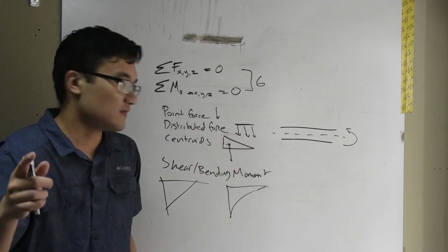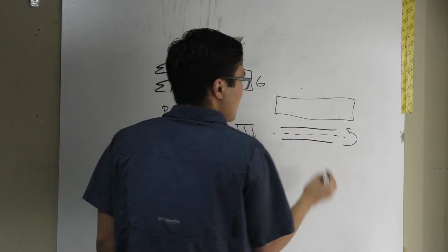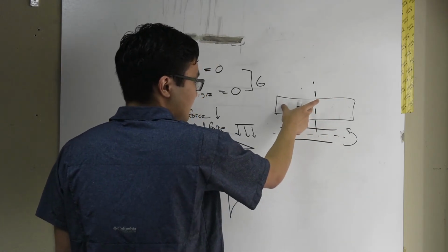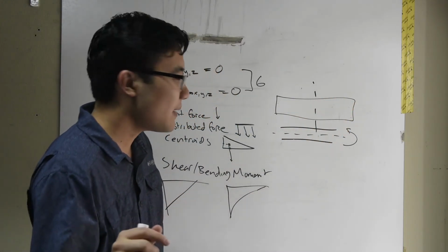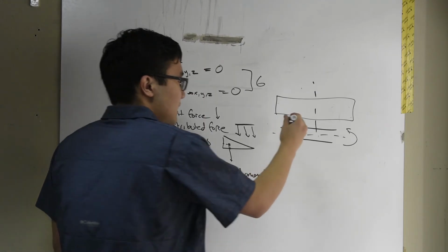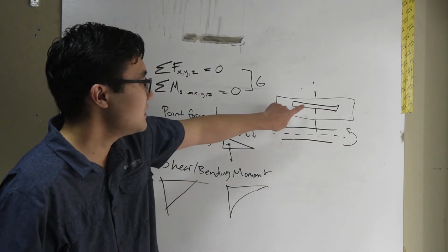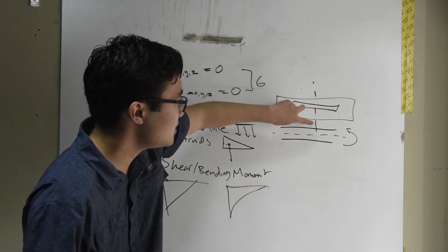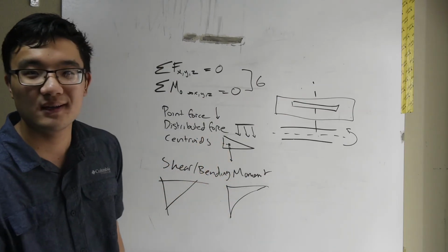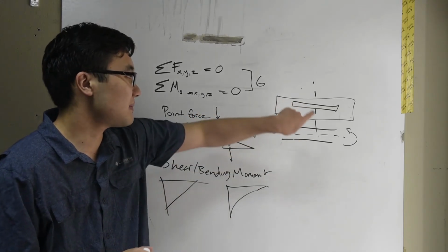There's a great comment last video by Kaylee about the wing. If we draw the wing, remember the wing is just a cantilever beam supported in the middle of both sides. Cantilever, cantilever. She commented, well, yeah, we were making a continuous piece of balsa wood through the middle, and now you guys know why. If we have a continuous piece of wood, this allows us to have continuity going through the area which has the highest shear and the highest bending moment. That allows us to make sure our structure is as strong as possible in this area.